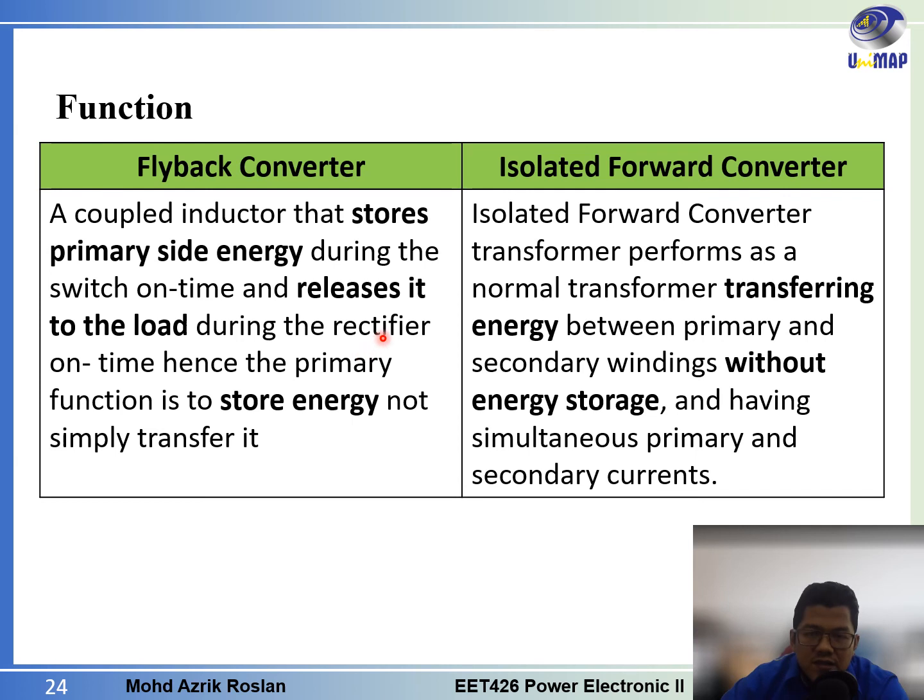The first difference is the function of the transformer. For the flyback converter, this is just a coupled inductor that stores primary side energy during the switch on time, and this energy will be released to the load during the rectifier on time, or in other words during the switch off time. Hence the primary function is to store energy, not to simply transfer it.